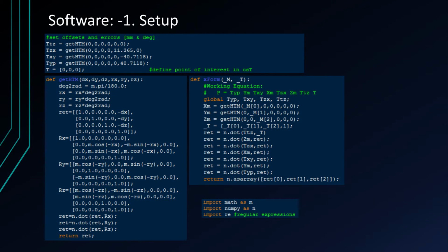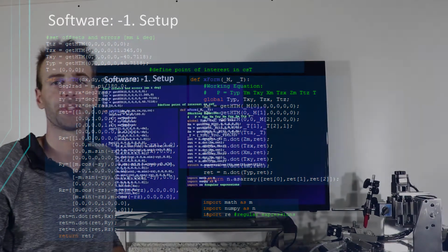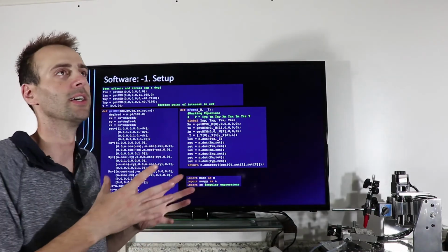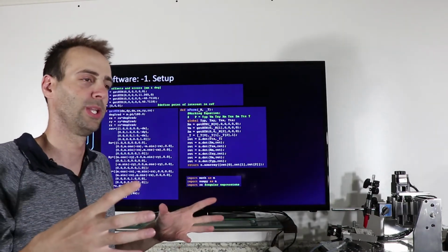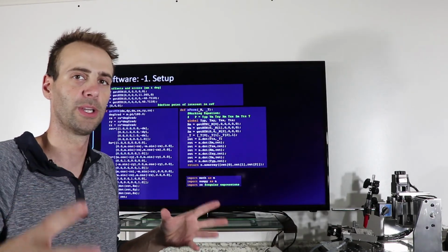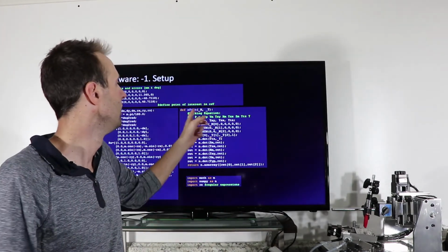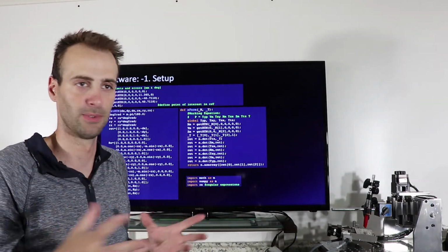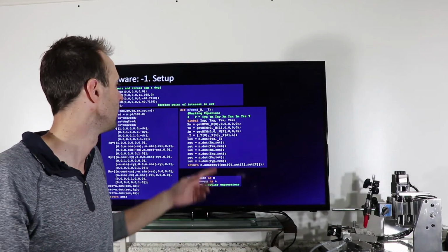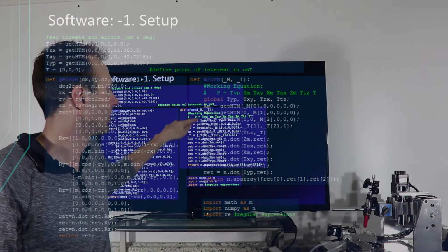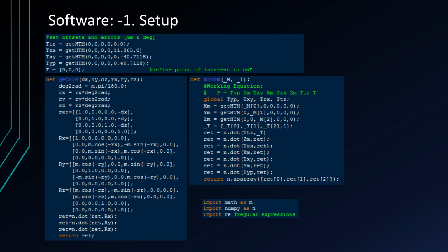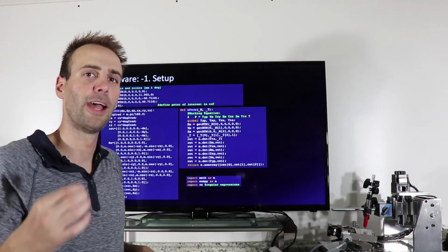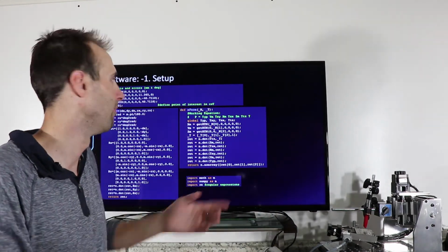As a precursor to what's coming next, I also have this transformation function. You tell it what position the X commanded coordinate would be, the Y commanded, the Z commanded, and then the point of interest on the tool, which for this application we just consider 0, 0, 0. Then it uses our kinematic chain equation to transform from the tool coordinate, using where the machine location is, into part coordinates.